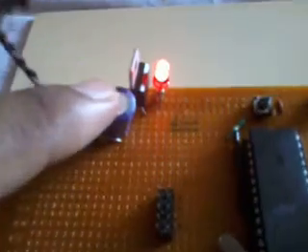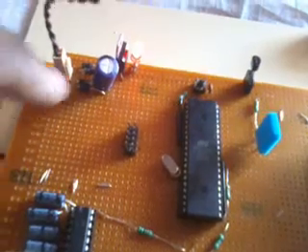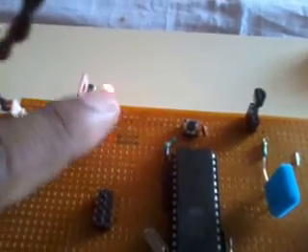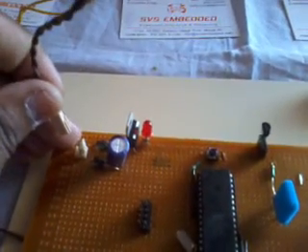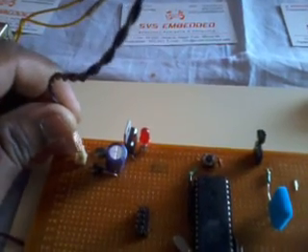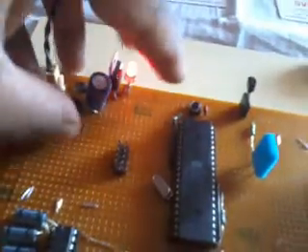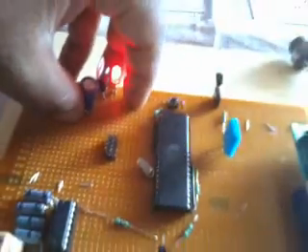Here I am using a 7805 regulator. Most digital logic circuits and processors need a 5 volt power supply, so that's why I used the 5 volt regulator. After that I used one LED. When the power is inserted, it should be on. When the power is removed, it should be off. So I am inserting the power, and that LED is on. This section is called the power supply section.